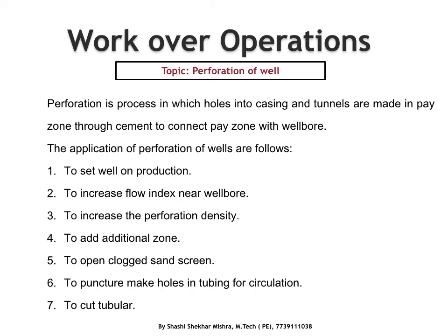So perforation is a process in which we make a hole in the casing through the cement and the tunnels in the pay zone. And this perforation is done to make communication between the pay zone and the wellbore. And there are many ways of doing the perforation that can be done under balance, over balance.